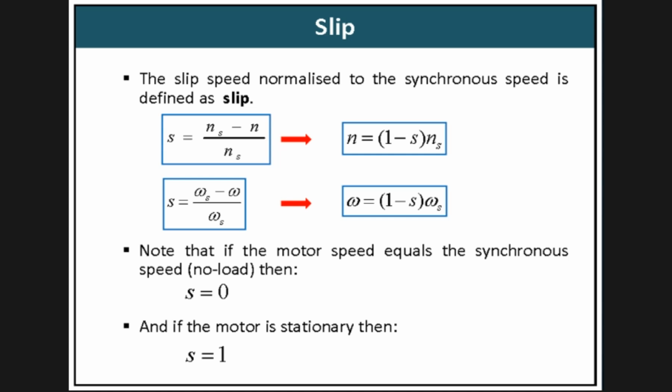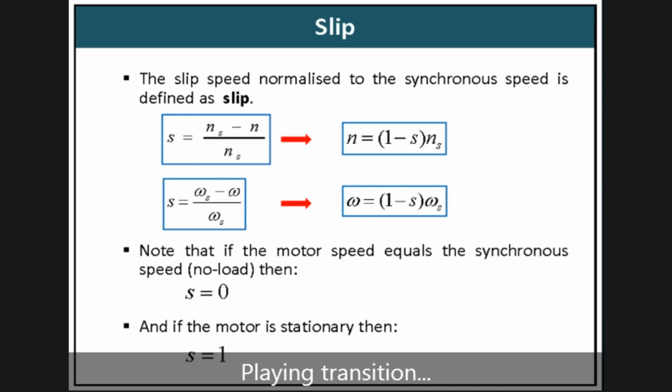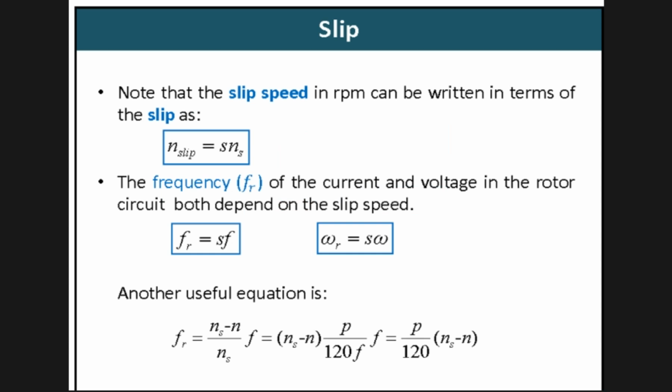So that way you can calculate the slip or slip speed for the induction machine. And the frequency of the current and voltage in the rotor circuit both depend on the slip speed.